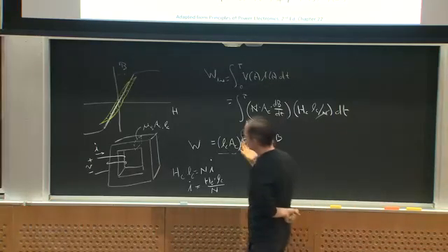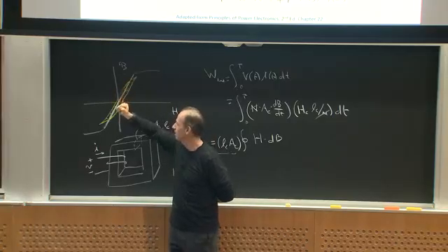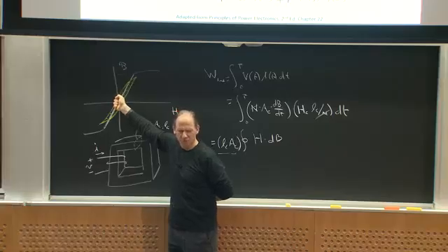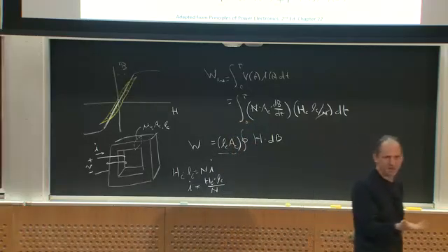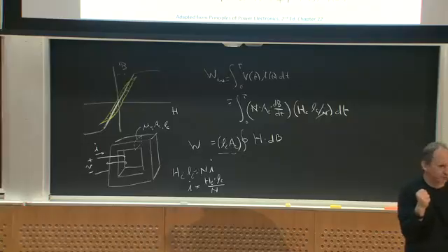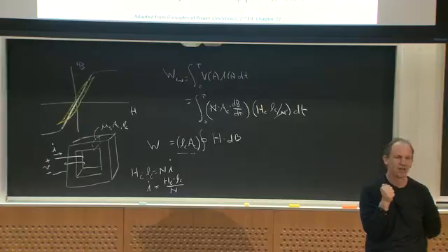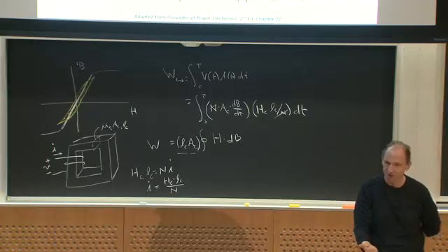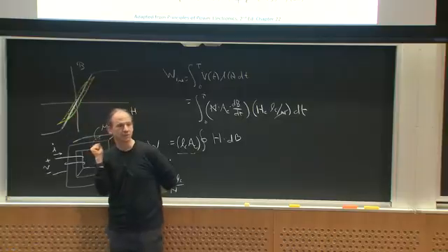This loss is sometimes called classical hysteresis loss. Okay? Unfortunately, while at low frequencies it's sort of proportional to frequency, when you get up to high frequencies, it turns out the shape of the loop changes. So it turns out that actual loss in many magnetic materials is not proportional to frequency. It's proportional to something higher than frequency. It just depends on the magnetic material. So that's one thing you've got to keep in mind. All right. So people sometimes talk about hysteresis loss, but what this hysteresis loop looks like is frequency dependent.